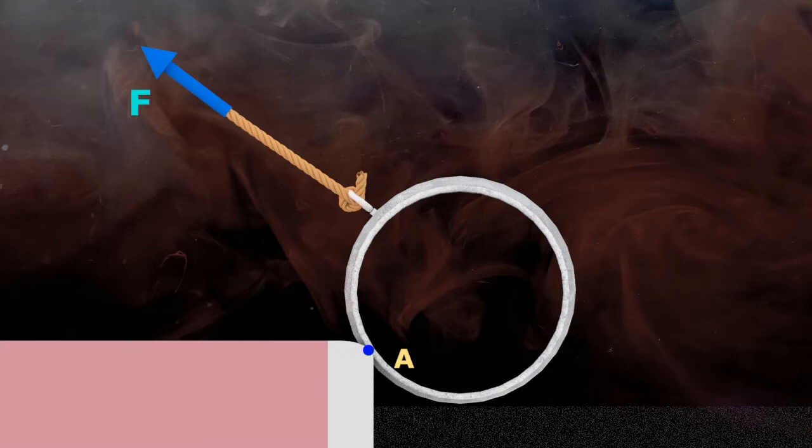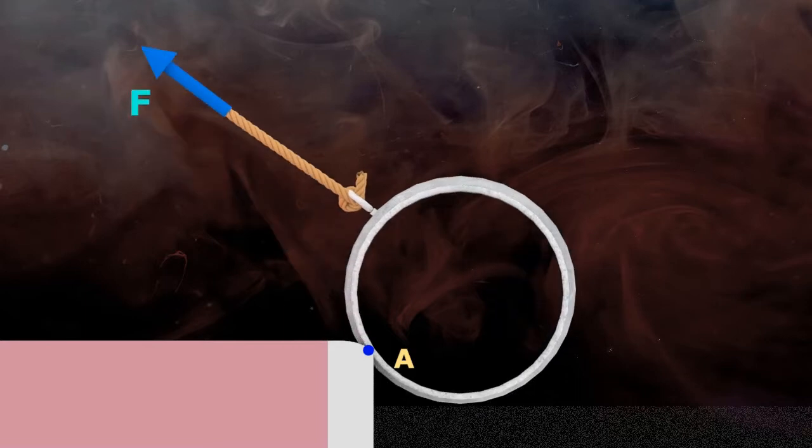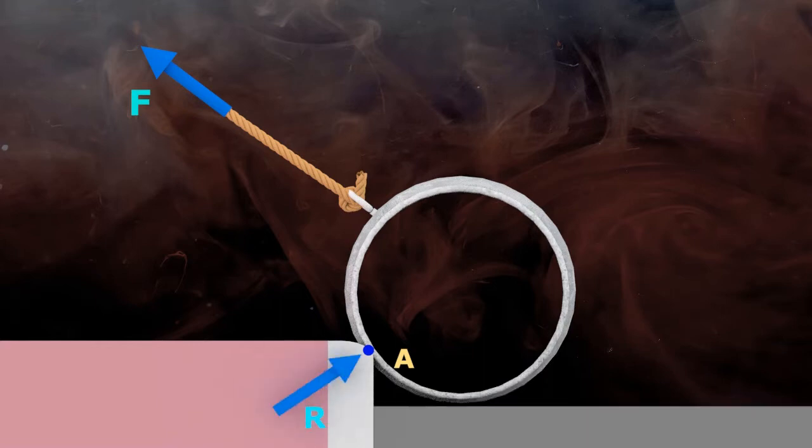Here, the pipe will be able to move in any direction freely under application of force but cannot pass through or push the footpath away. So the curb restricts this movement of pipe and so reaction R will be developed in the opposite direction. Before application of force F, pipe was touching the pavement too, but the force is applied such that pipe is little bit lifted so the contact with ground is lost and there won't be any reaction from the ground. No other body is in direct contact to pipe, so only one reaction R will act at point A.